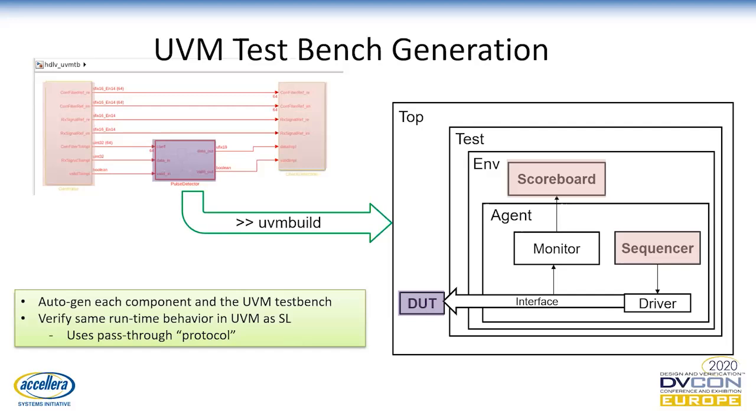Now, there is also the UVM testbench generation with a command that's called uvmbuild. With this command, we basically generate the SystemVerilog top model, a kind of skeleton for the UVM environment. Everybody that is familiar with SystemVerilog, and I guess many of you are, knows that many blocks and many files are involved.